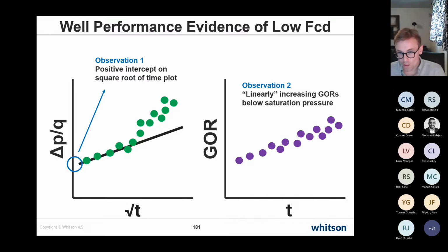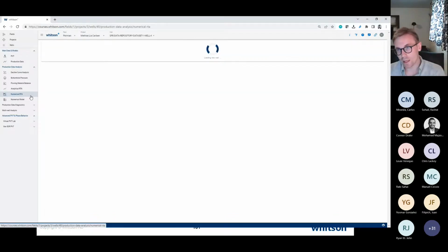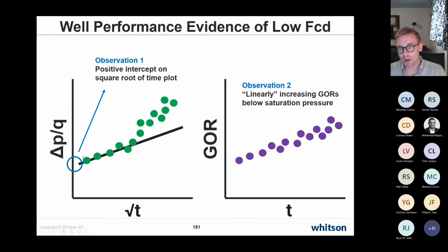At least what we do, and what I always advocate, is to not include it by default. But if there are a lot of things that suggest, in terms of just these simple diagnostics, that you should decrease your fracture connectivity, which by default in the software I think is set to probably 1,000 if I'm not mistaken, then you take that down to 100 or 50 or 20, and maybe even lower.